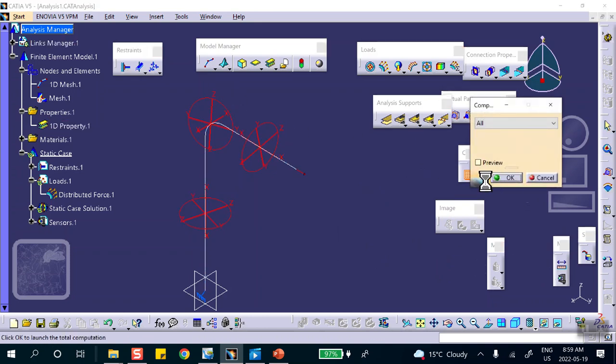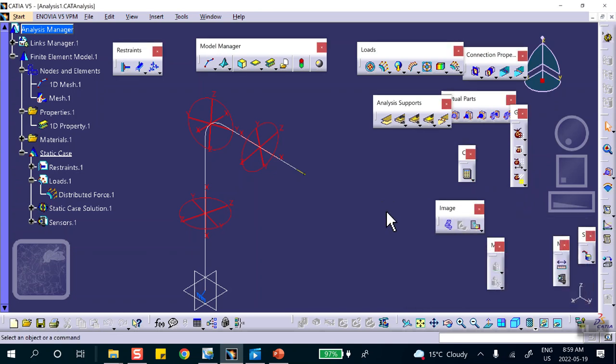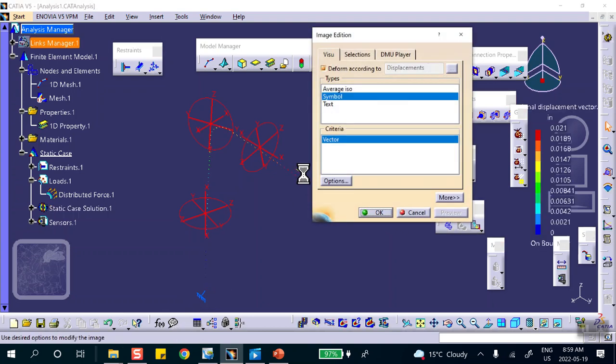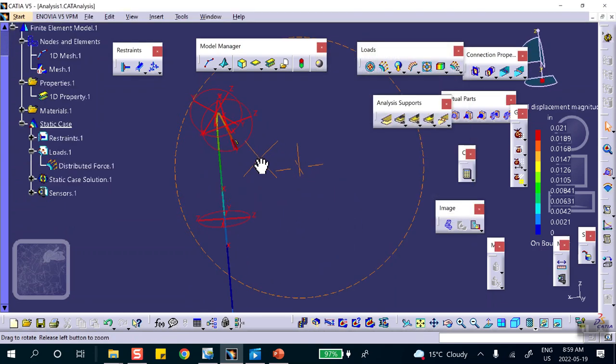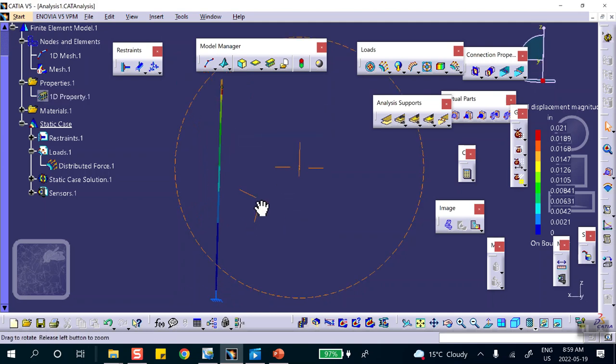the top member is primarily axially loaded. The bottom member is primarily bending, not torquing, okay? And you can look at it. It's coming in that direction. See, it's coming towards you. Let me hide these things. It's coming towards you. It's not going sideways. If the load was sideways, it would make this thing torque and go.